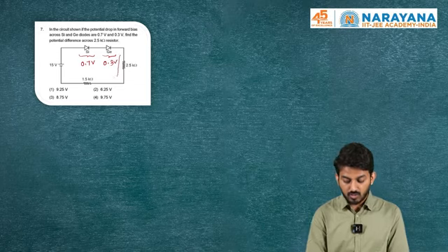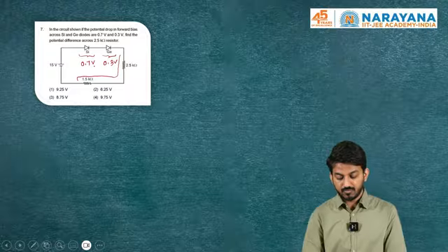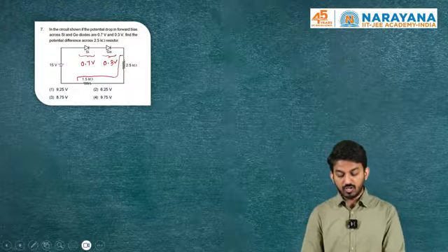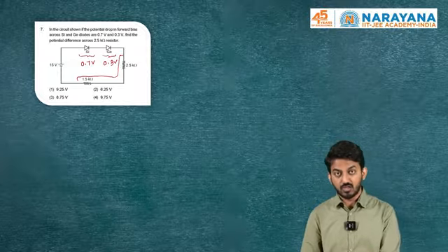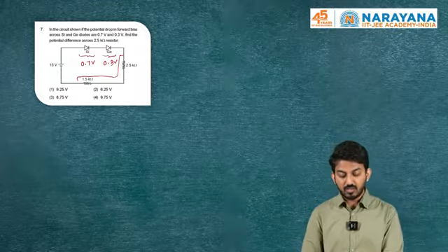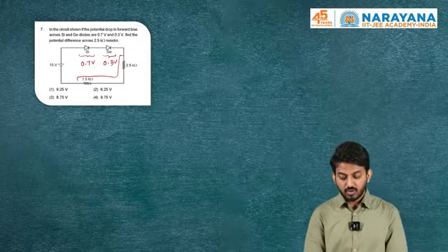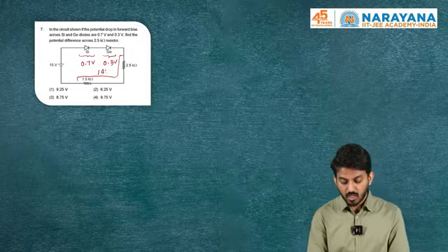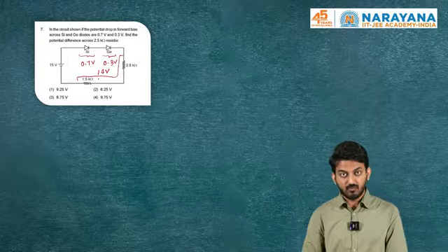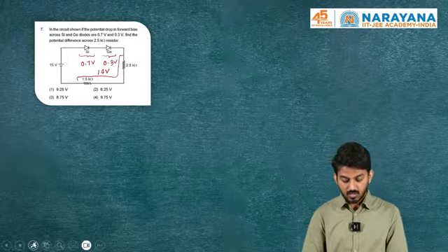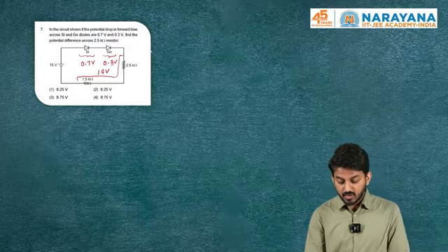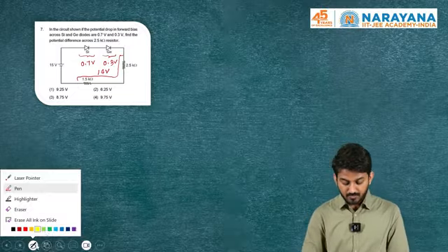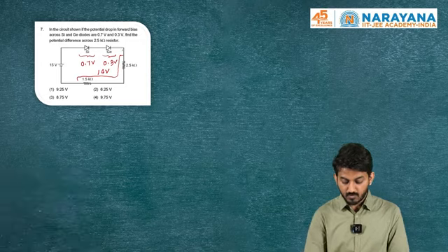Now, total voltage across the resistors here. The total voltage across the system is 15 volt, out of which 1 volt, 0.7 plus 0.3, 1 volt has been taken by the diodes. So remaining 14 volt stays here. Now, so current through the circuit, if I mark current through the circuit, some I.